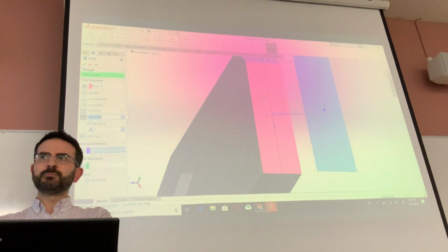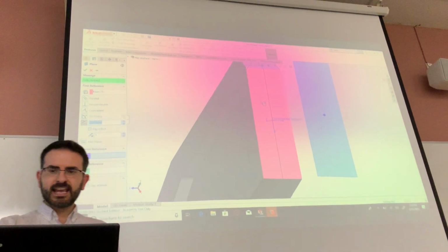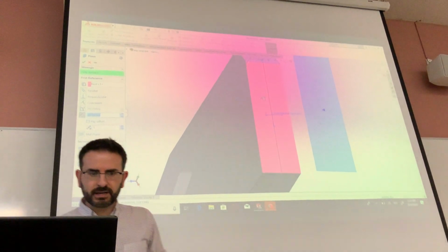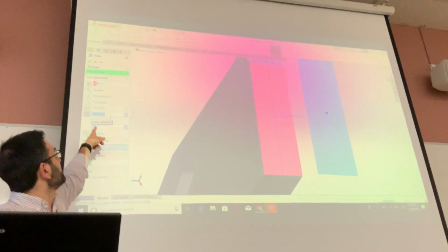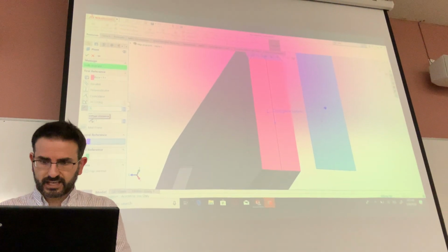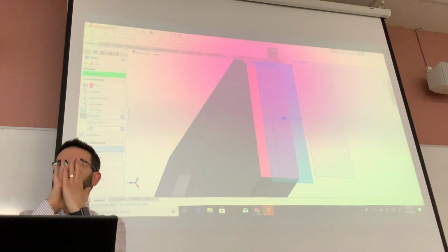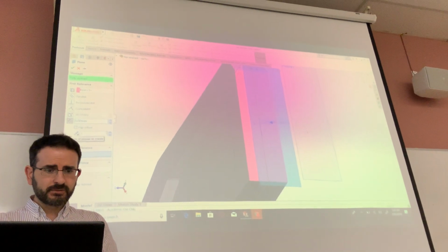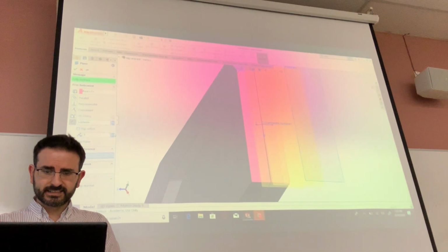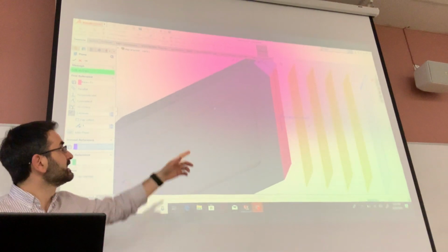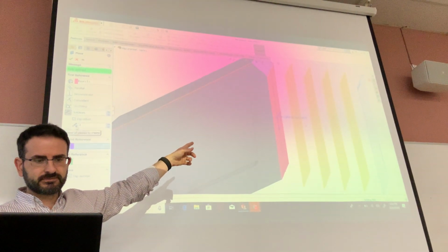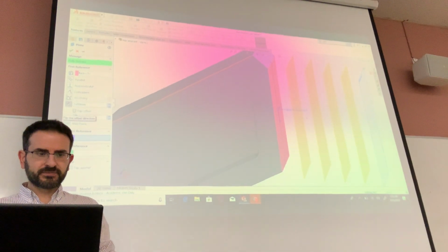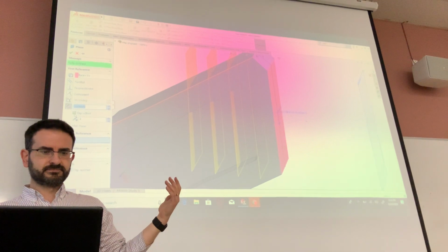the face becomes pink, that's the reference face, and now it has created a parallel plane that's offset by some certain amount. By default, it remembers 25 from before, but I can make this 5, and now it's creating a plane that's much closer. You can make it 100 and make it much farther. You can even do multiple planes; you can create as many planes as you want by just increasing this number here. Or you can flip the offset, and it makes it on the other side.